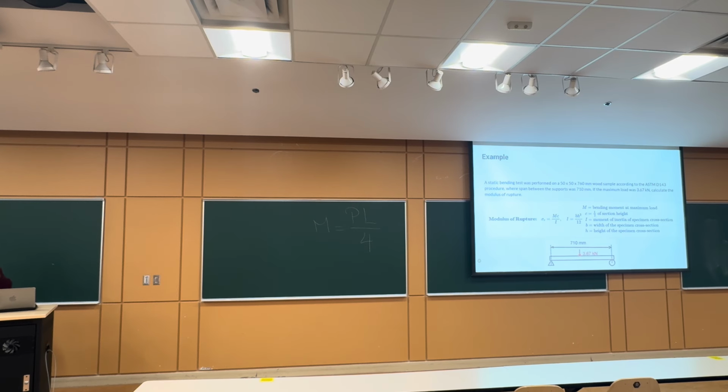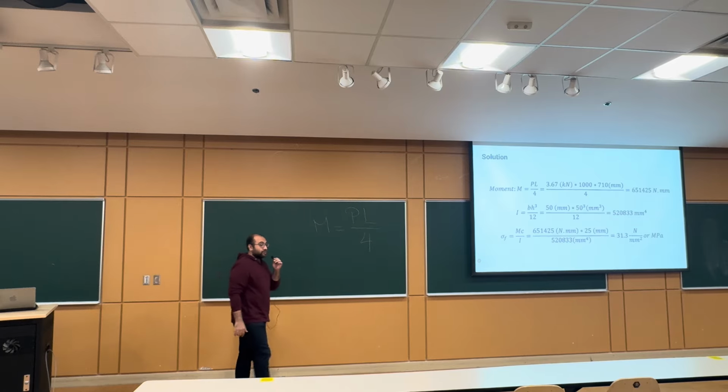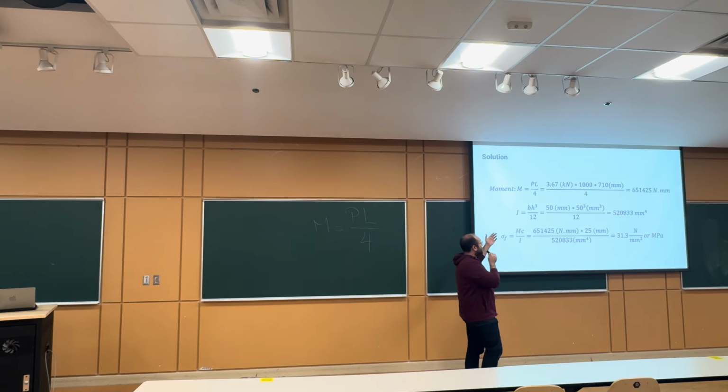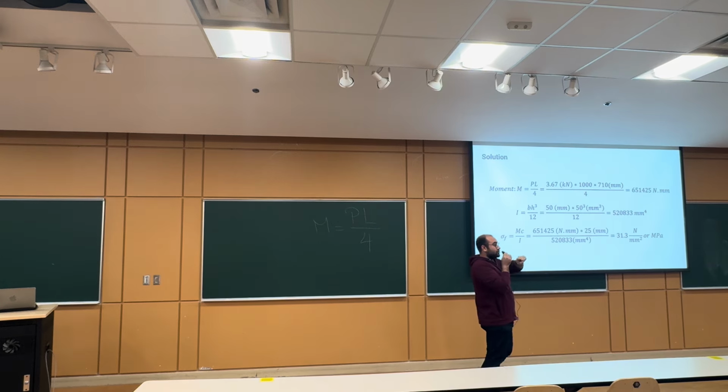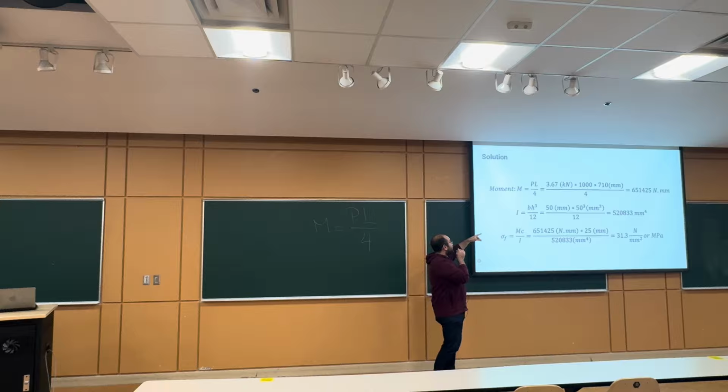So, any final answers? Yes, please. 31.2 megapascals. Exactly. To solve this, we should start with the calculation of the moment. So, we start with the moment calculation, which is P, the load, multiplied by L, which is the span length given as 710, divided by 4.